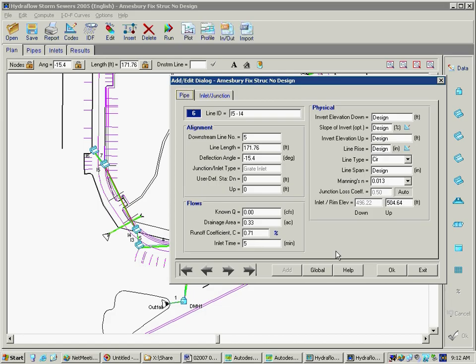All right, I have a quick question. Yeah, go ahead. If you put in, say you have a subcatch that's catching water from off-site, say the time of concentration is 15 minutes. If you enter the values in with the area, the C value, and that 15-minute TC for that one inlet, will it use, now that leg has a total time of concentration of above 15 minutes, even though the rest are 5. Does it cumulatively add the time of concentrations as it goes down through the flow lengths? Opposed to if you just enter a known flow, it can't do that, it just has that flow and that's it.